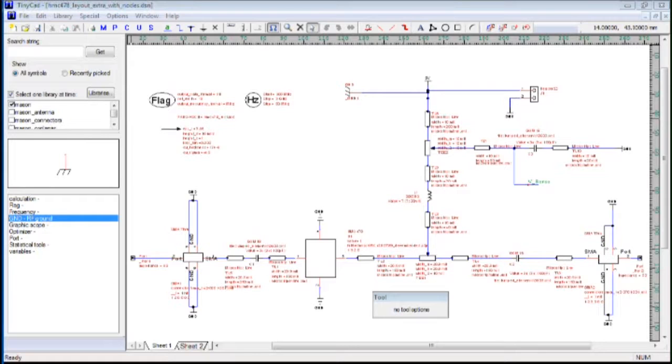Up here, we have a header that provides this DC 5 volts. It's RF grounded with that component. So for this particular part, we don't have to provide any simulation information. There's no file, there's no primitive data that's associated with it. All we have to do is provide the package type. And here I'm using a file-based, XML file-based one, which means that it can automatically place this header. But we don't have to worry about any sort of node mapping with this.